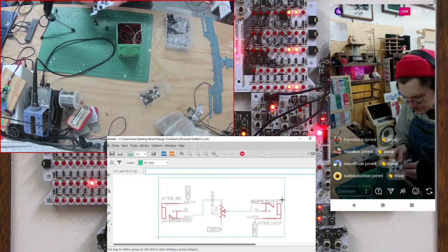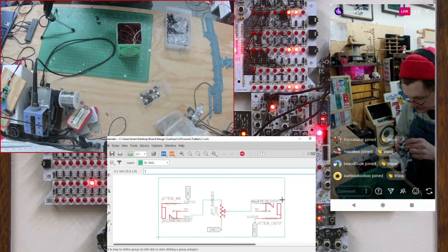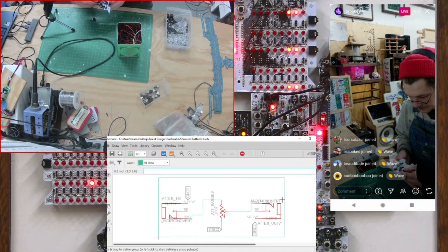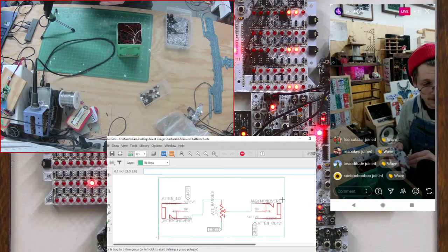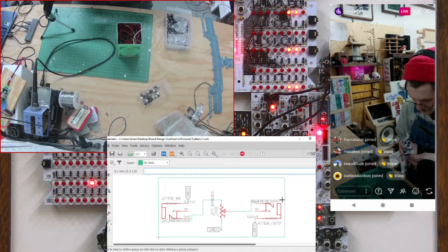between modules. It's a really good unit when you're starting out and you're afraid of, say, sending too much voltage to one of your modules, or one of them isn't calibrated right and it's clipping and making strange noises when you're feeding the signal in. Maybe you're getting a popping sound or some sort of clicking like that. You could throw one of these in line with your signal, put it before whatever your final destination is, and that'll help adjust how much is going in and out.